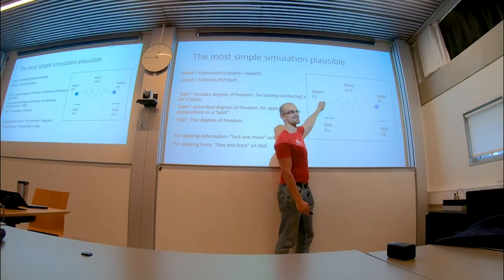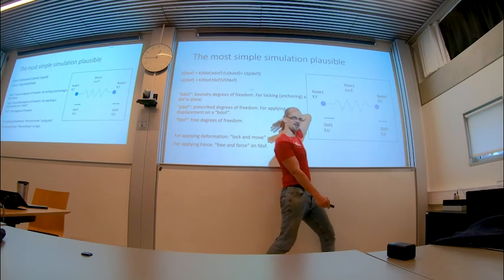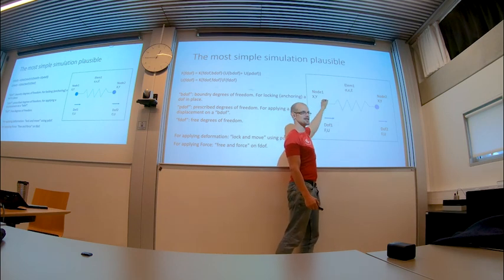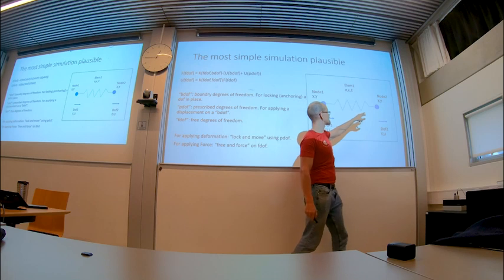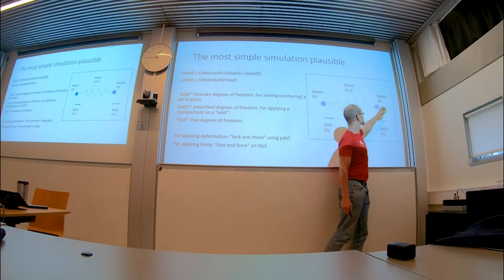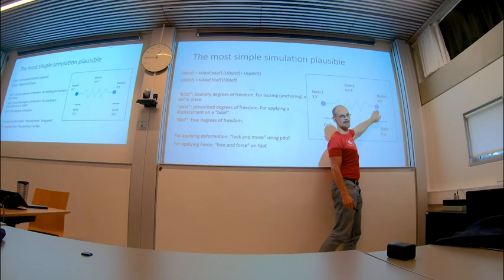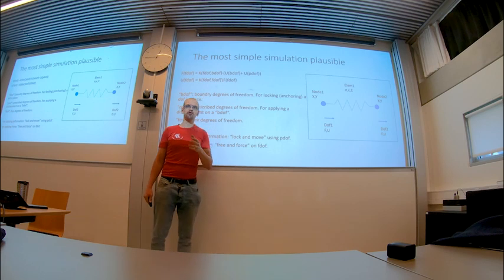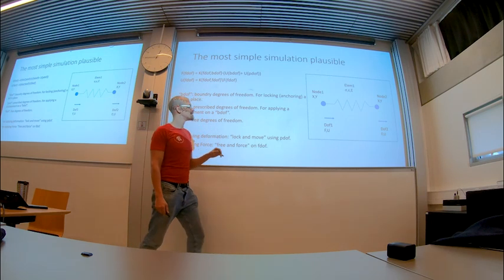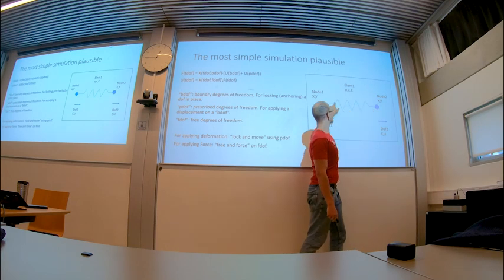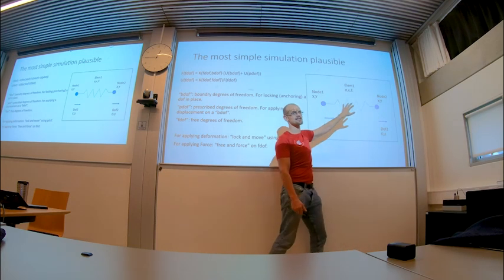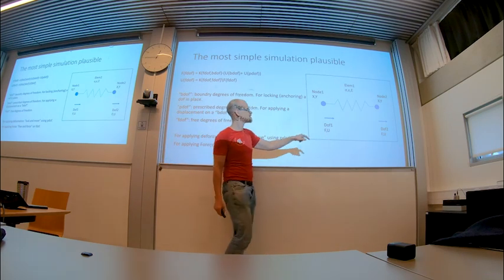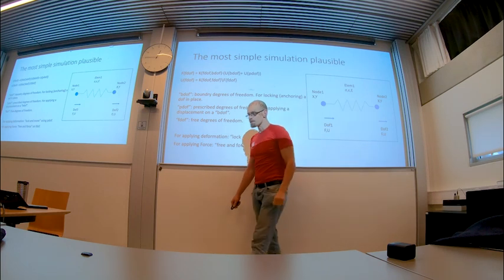So something has to be anchored, otherwise if it's just floating, you apply a force, it just floats off to infinity. So you anchor it somewhere, and you can change the position of the anchor if you want, using the first equation there. And then afterwards you apply a force on it to move it, and then you find the displacement on the floating one, the free one. And that's all you can do with elasticity. Elasticity cannot do anything else. After it moved, the force was applied, it moved, the distance between the points changed, and you can calculate what the stress is, or the pressure, or whatever it is, inside the element. As long as you know the stiffness, you just find the properties.